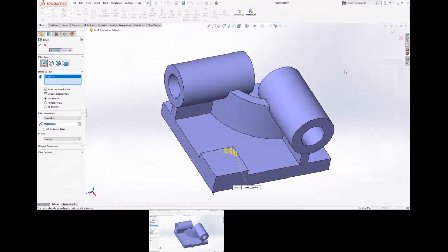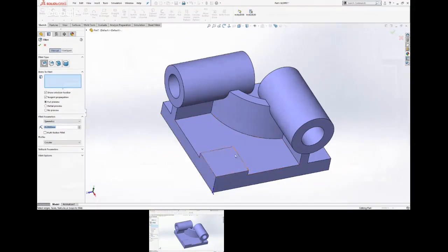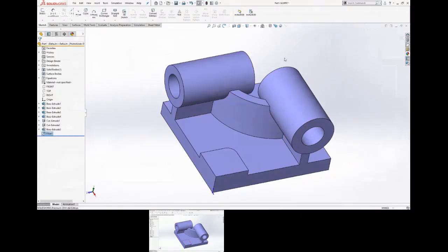How many of you use 3D mouses? I know you have. Does anybody else have one? I'll tell you that the driver for those devices will tend to turn that feature off at random times, the selection through, how I'm able to select that edge. I think it's select lines through graphics or something like that. The drivers for those devices will turn that one off, and it'll turn off some other dynamic highlight option in the software. It bugs me a lot that it does that. But it's kind of carried over through the drivers through years. I don't know why. So if you see it turned off and you're using one of those, you'll know why. In fact, I think at one point I actually had a macro that when that would happen, I would just click the button and it would turn them back on for me.